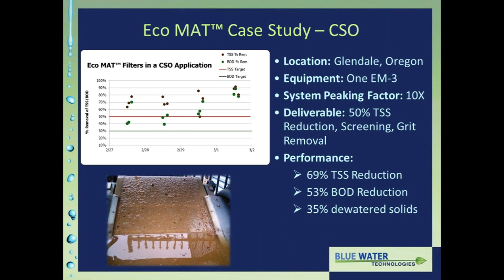And a lot of times that's tied into what kinds of constituents the runoff might pick up, whether it's picking up oils and various constituents like that, and also the strength of the sewage that it's being mixed with before treatment, if any. So again, very appropriate treatment system in a pass-through screening application for combined sewers and overflow situations.